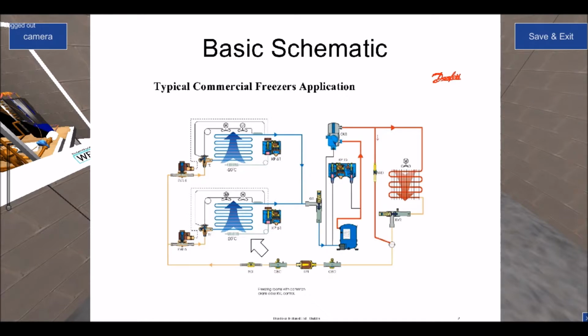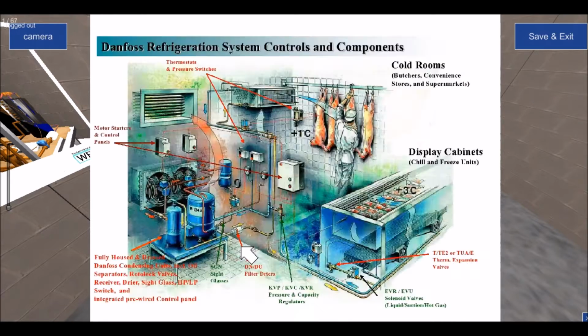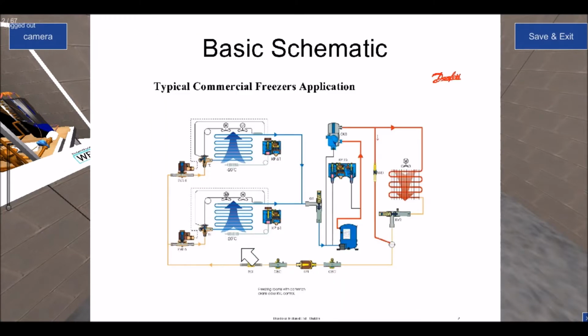Now, as soon as the room temperature is reached, so in our previous one, our stat says plus 1 degrees. As soon as that room temperature is reached, there's a little bellows in here. And again, you've got your spring pressure that you have set, and the bellows pressure. Those two opposing pressures will decide whether the switch is closed or open.